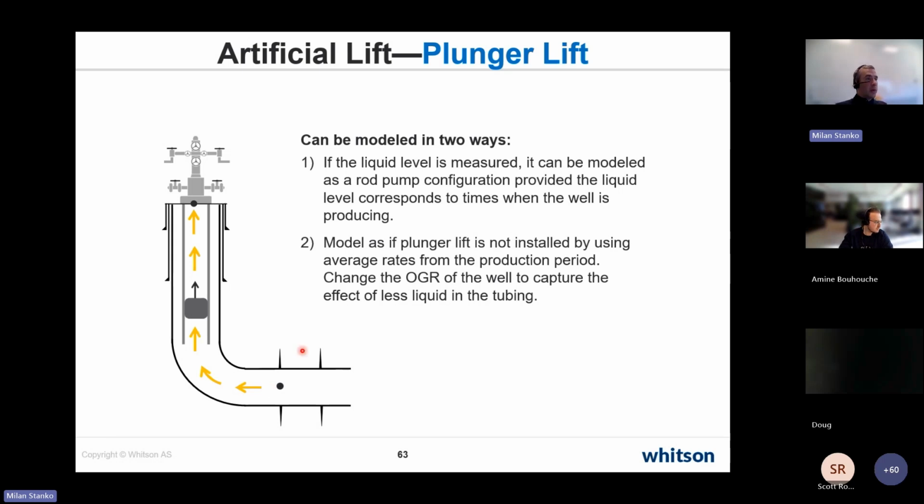Okay. Otherwise, if you have a liquid level measurement, sometimes with this plunger lift, if you have no bottom packer, we typically do that too, because then you store some. So when the pressure is building up, if you have the bottom packer, then you only depend on the volume of the formation, and it might take a while to fill up. So what some people do is that they also use the annulus as a lung, some sort of an additional volume. Okay, and then that's increasing, and when they let it flow up the plunger, then all of the gas accumulated here is going to flow up.